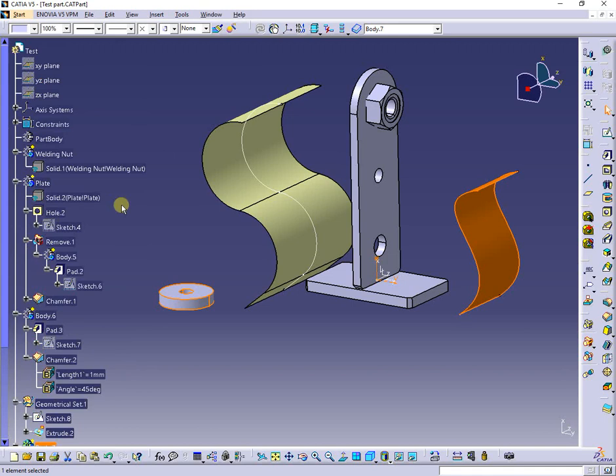From the Tools toolbar, in Part Design and GSD module, options can be selected: only current body, or only current operated solid, as shown. I want to show you how activating these options affects each kind of body previously presented.